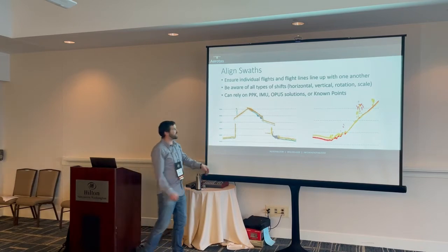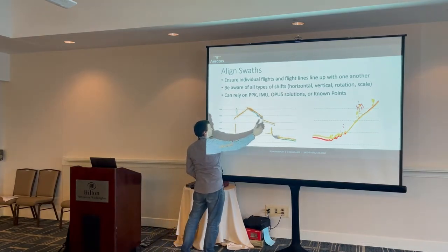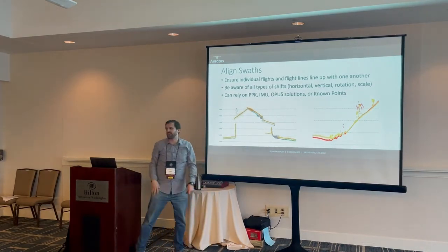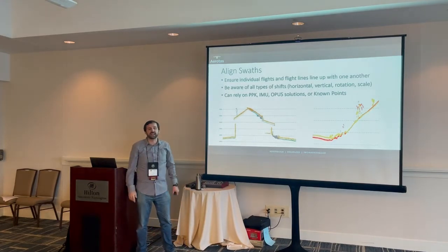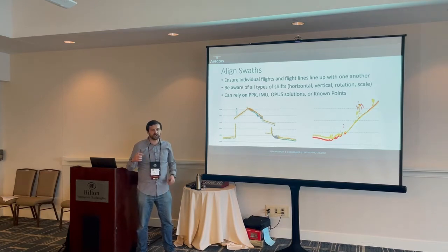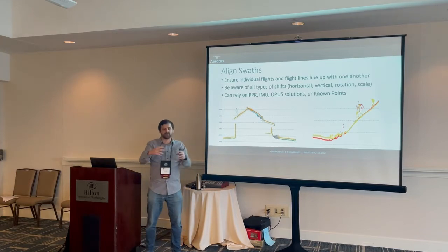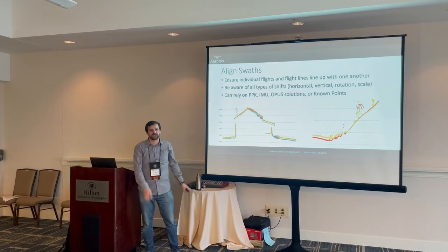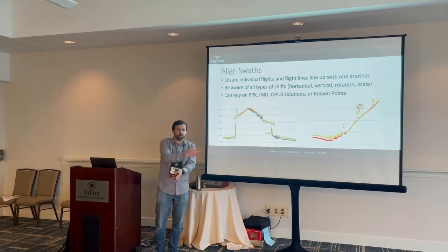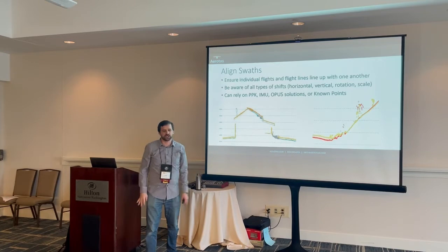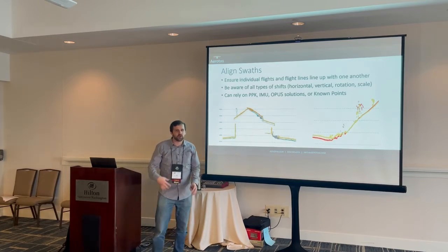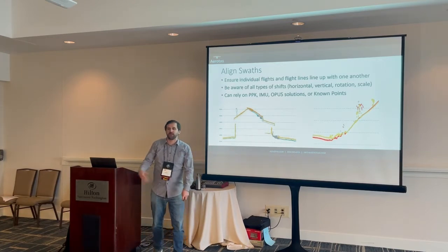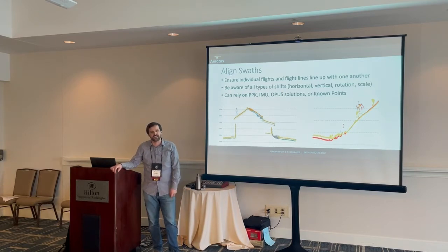But that's one where you can actually get this to be shifted, you know, maybe it's a little left, a little north, and a little down or something like that. But finding those points and actually aligning them by picking known points, that's one way to do it. Finding features and drawing the perimeter of a house so you can tell exactly where to shift it. I always like doing my X and Y shifts first and my Z shifts last. So finding those identifiable points in 3D to get those XY shifts is a little bit tricky and requires a little bit of trial and error, but that's my favorite workflow for shifting those together.